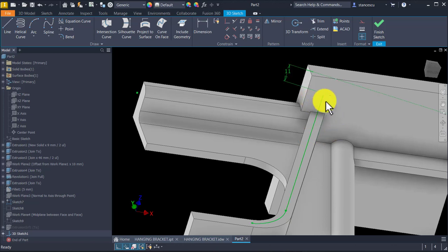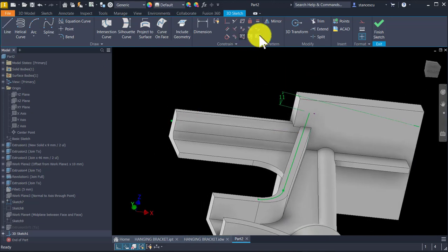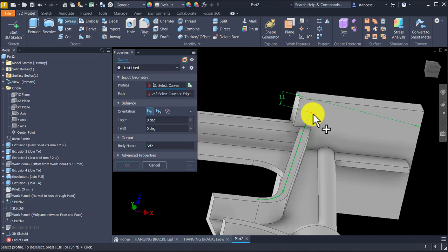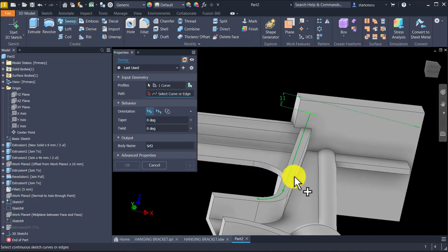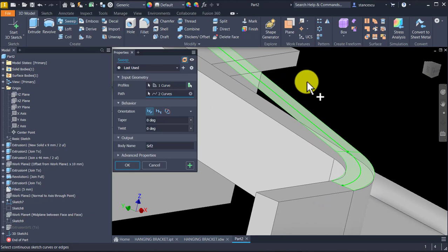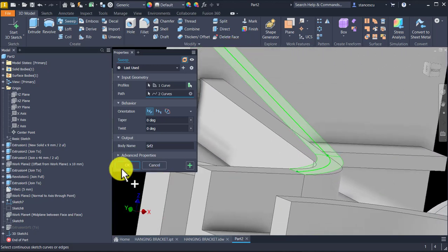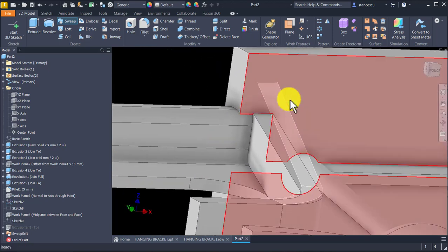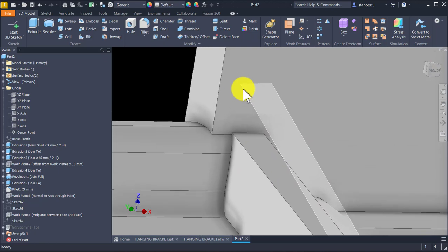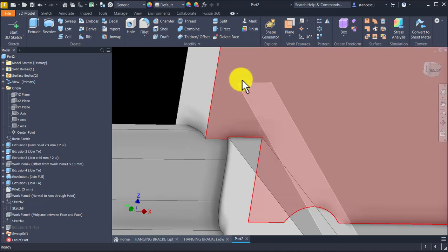Then, since this curved contour ends on this segment, I can apply finish sketch firstly. I can apply sweep. I want to sweep this entity as a surface mode on this curve. Now I have a surface here. Okay. On this surface I project this line because I want to section. I don't need that extension. Yes, triangle, that triangle, I don't need it.